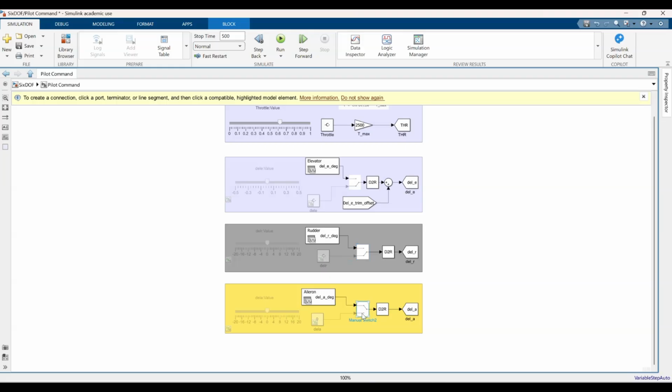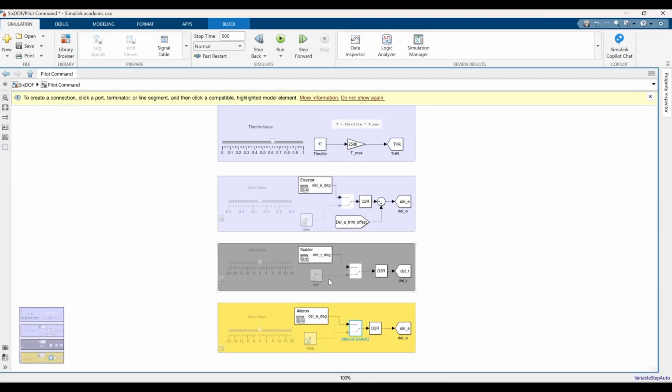So if you double click on the manual switch block, you can toggle the switch. I will toggle the switch downwards because for today's analysis, I will use the slider. So signal editor can stay. It need not get commented out.